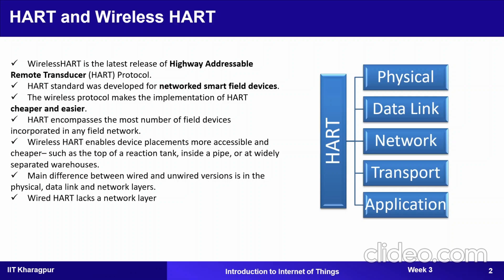After that, the super frame controls the timing of transmission to ensure collision free and reliable communication. This layer also incorporates channel hopping and channel blacklisting to increase reliability and security. In HART, the users who are going to send data do not send the data through a single channel only. Since there are 15 channels, every time a transmission is made, the channels are switched. This is called channel hopping.